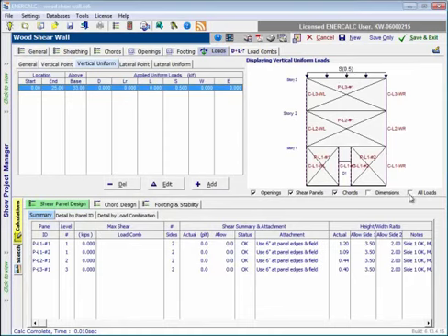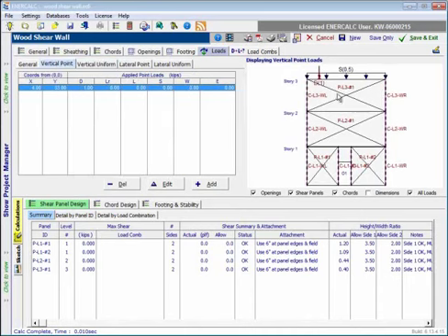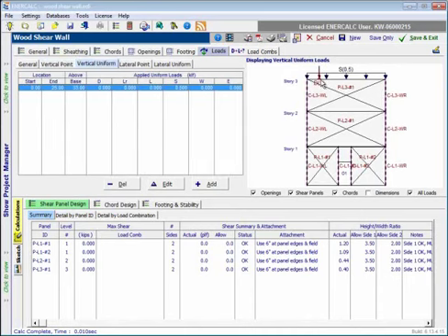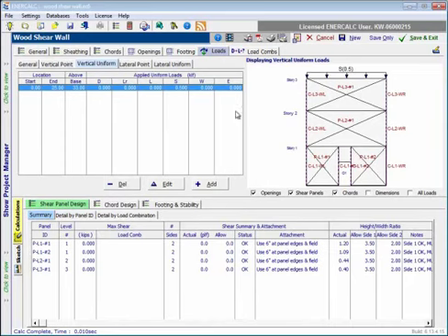Now I can come down to this all loads checkbox, and I'm supposed to see all of the information for the different loading types. So there we can see, I had to just refresh the screen in order to get that view, but we have both the dead load, that's a point load added from another tab, as well as the vertical uniform load from snow added on the currently selected tab. So that is the function of this checkbox, and we can see that we just have a refresh item there that needs to be clicked from one tab to the next to get that to refresh.